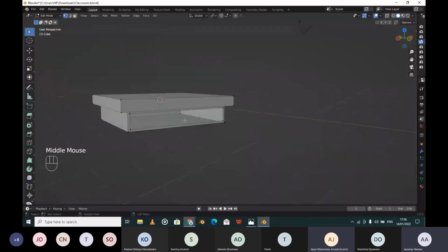So when we created this inner layer, our deck doesn't have any thickness to it. If this was a real table and you tried to keep anything on this deck, this part would probably break off immediately because there's no strength to it. So what we can do to fix that is to add another surface on top of it, and we can do that by simply filling up these vertices.